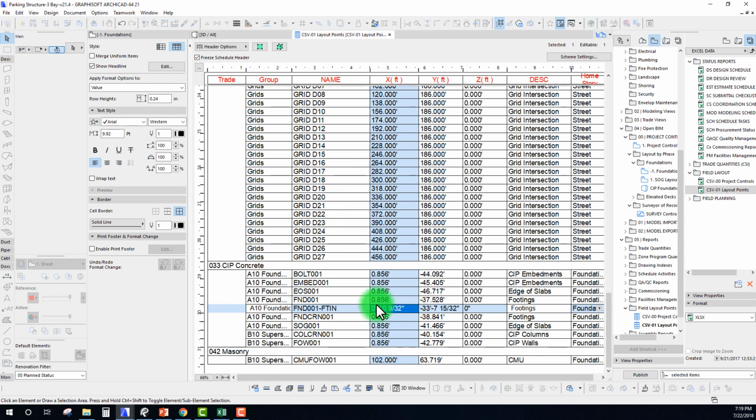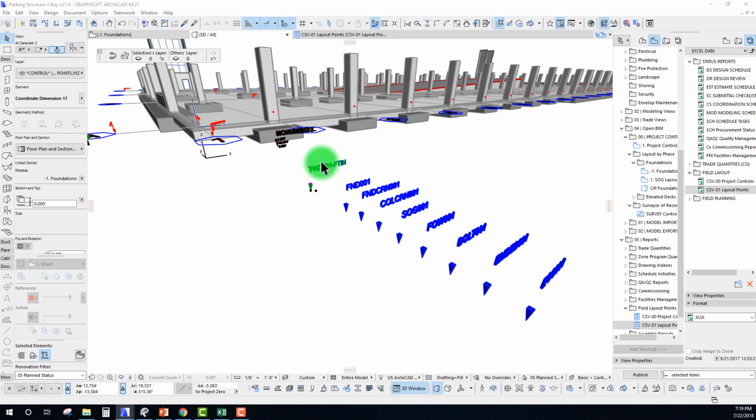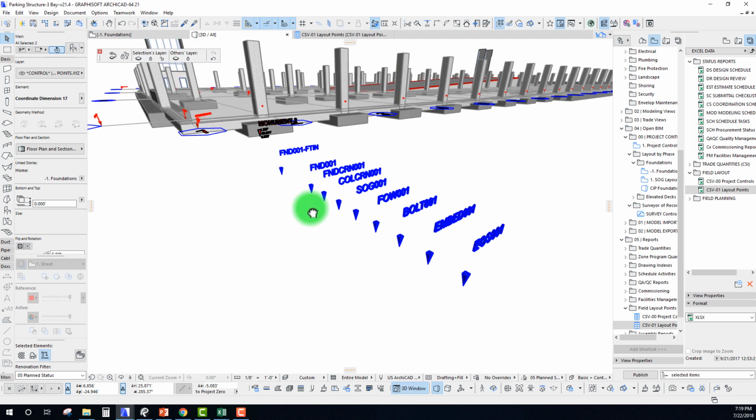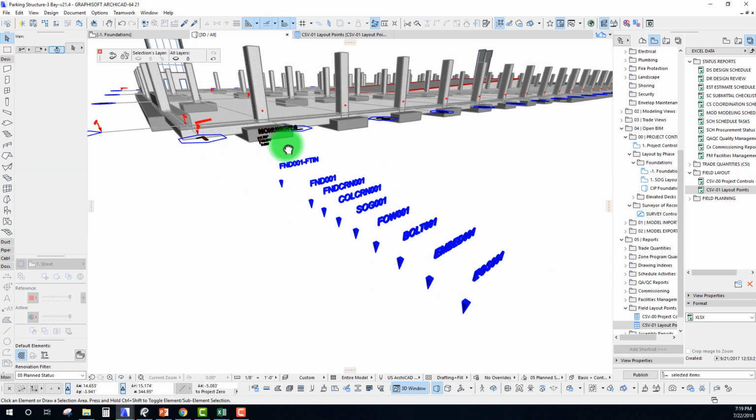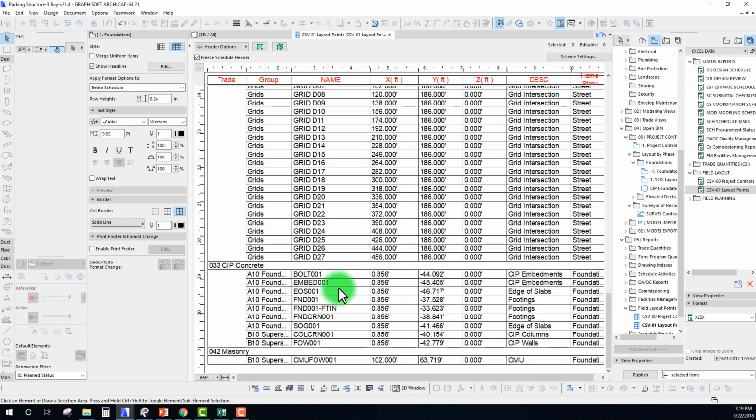It'll still remain on feet and inches. And so the workaround there is just to modify the value here. Sometimes I just push it up a foot and then push it back down a foot, so it's at that same exact location that it was before. And just by doing that quick modification, it will actually update, and that foot and inches will now be based off our latest project preferences that we had in our working unit. So that's the workaround there.